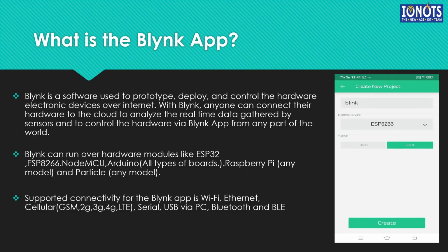Now, there are three major components in a Blynk platform. Number one is the Blynk app. It allows you to create amazing interfaces for your projects using various widgets they provide. Blynk server is responsible for all the communications between the smartphone and the hardware. You can use the Blynk cloud or run your private Blynk server locally. It is open source, could easily handle thousands of devices, and can even be launched on a Raspberry Pi. Blynk libraries. These are the libraries for all the popular hardware platforms in order to enable communication with the server and process all the incoming and outgoing data and commands.